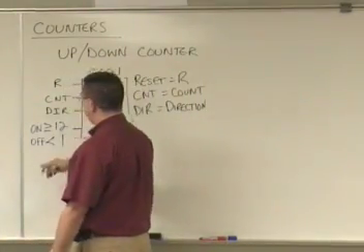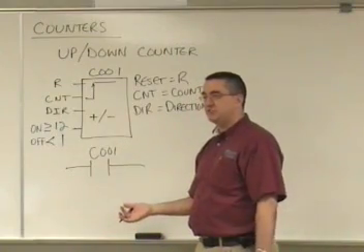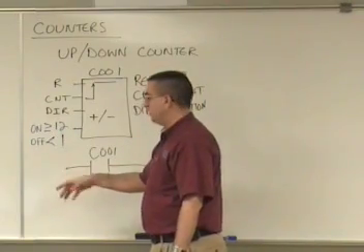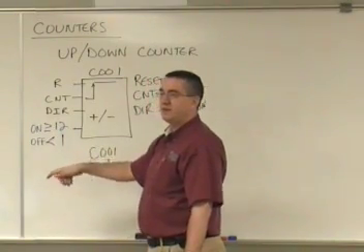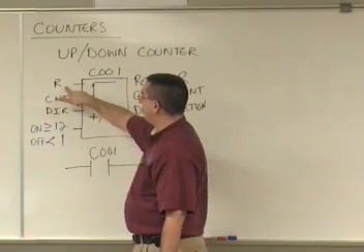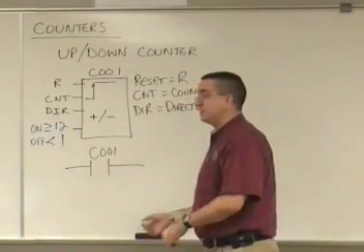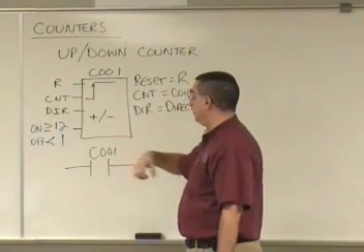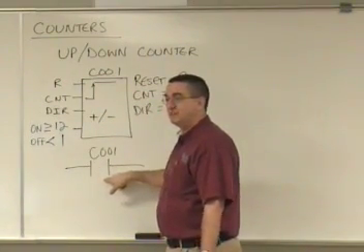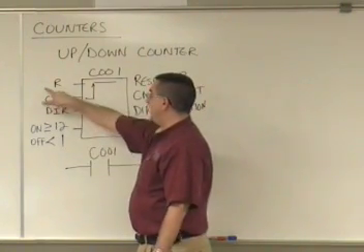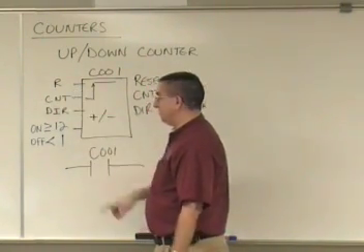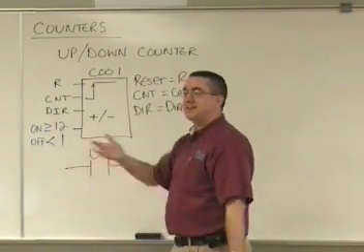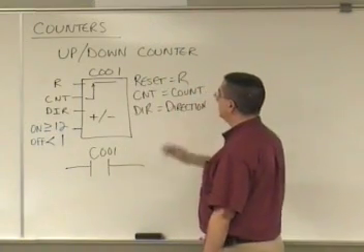All right, so typically, if I'm not sure what to use in the off threshold, if I know that I want it off when it's reset or when it's set to 0, I want to make sure that's at 1. That way whenever I reset this counter using the reset pin, that reset is going to plug a 0 into the current count. And when it plugs that 0 into that current count, what's it going to do? It's going to reset that bit. Exactly right. If I had this at a 0 and I energized the reset pin, it wouldn't reset the bit, because it'd be equal to the off threshold. And we know it needs to be less than that off threshold. So that's the one thing that's a little strange.